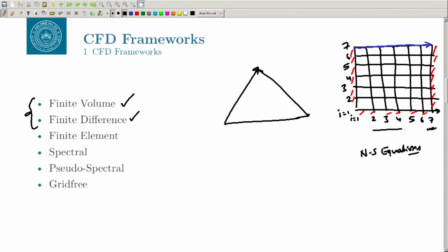So, what you can do rather is basically you can create a grid which is maybe something like this, you can fill in elements the way you want, okay. You might want to ensure that there is a boundary layer close to the wall, okay, so that we are able to capture the velocities, the boundary layer properties well, okay. Let us say you made a grid like this.